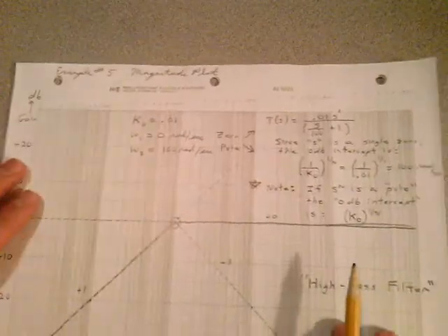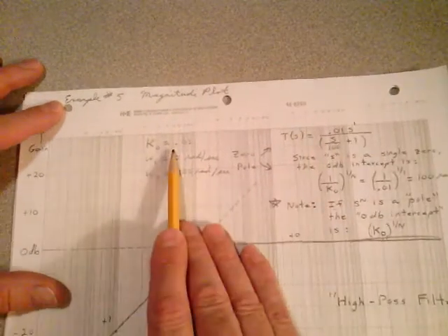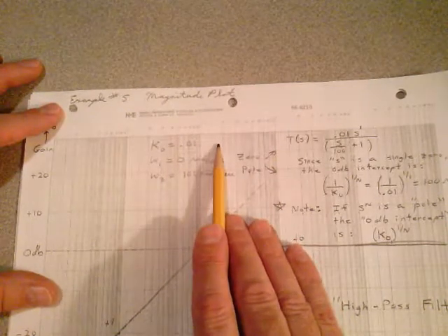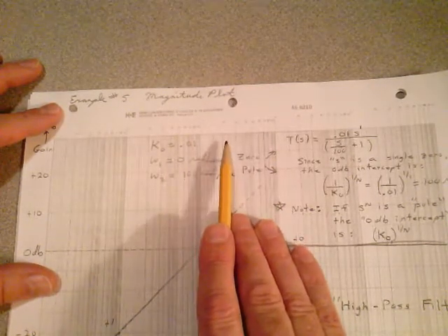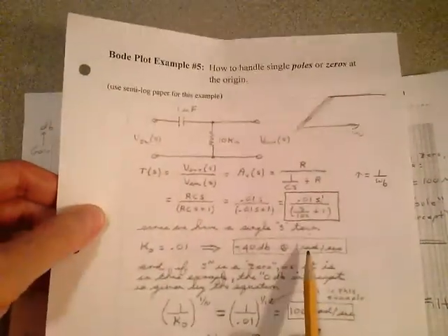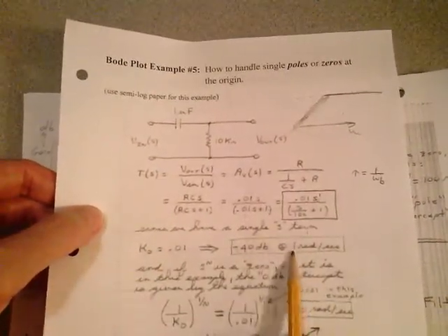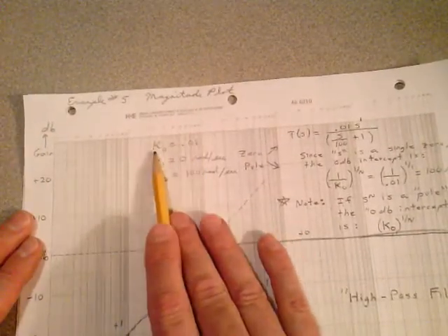The Bode plot here is where I transfer everything over, and I did here. Here's my transfer function. It's a single S term, so I'll put a 1 up here. Because I have that single S term, my K0 is still the 0.01. There's the 0.01 for K0. Now I could take 20 times the log of that, but that's going to give me a dB at 1 radian per second, like I said here on the previous page. But we're not going to write this down up here, because that's not how we're going to use this K0 initially. We're going to use this K0 in this equation here to get that 100 radians per second.